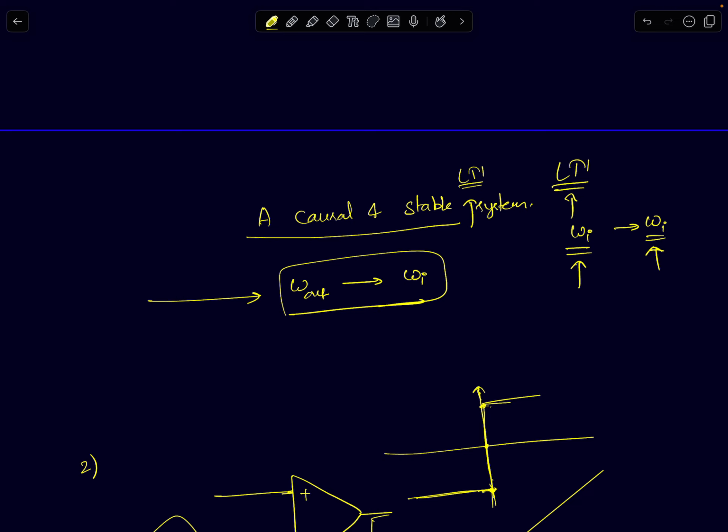What we have in the circuit, the question that the student posed, was actually a resonant system. It's a second order resonant system with poles on the j omega axis, and therefore it is no longer a stable system. It is a marginally stable system. As far as a circuit engineer is concerned, we can still call it an unstable system, because of which it has two frequencies, omega I and omega naught. So this will be true for marginally stable systems.